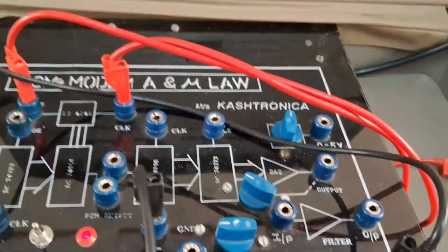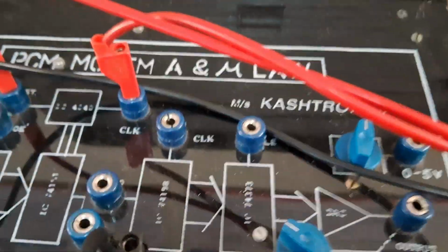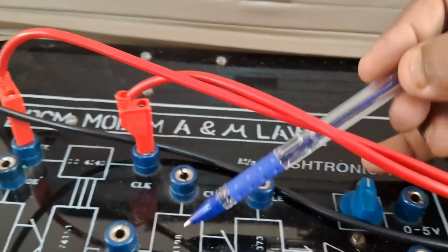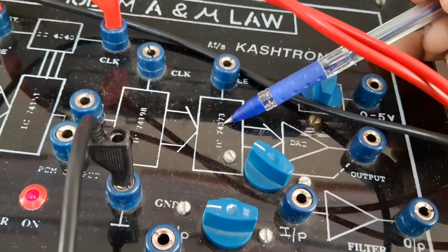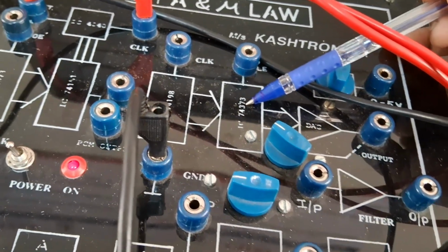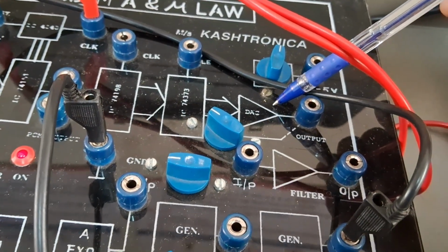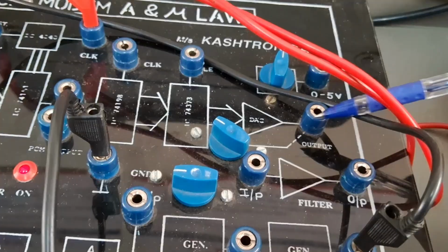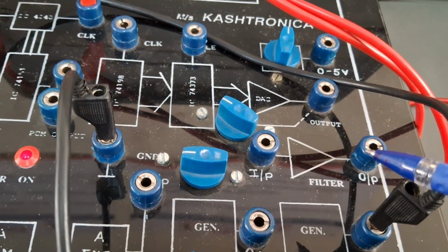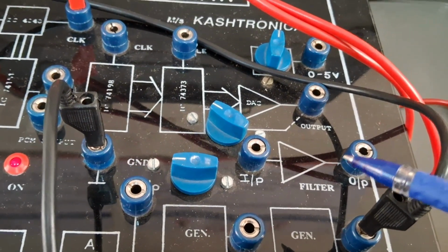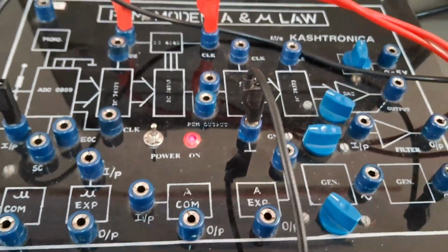Now coming to the decoder side, what is at the decoder side? You have once again a serial to parallel converter, which is over here. Then there is the latch which has been holding over here, and instead of the ADC, now it is going to be the DAC, that is, an R2R ladder type of DAC which has been used. This R2R ladder DAC output is passed through the low pass filter, and what you get is the LPF output back again, right? So these are the synchronized waveforms of the PCM output which has been shown.